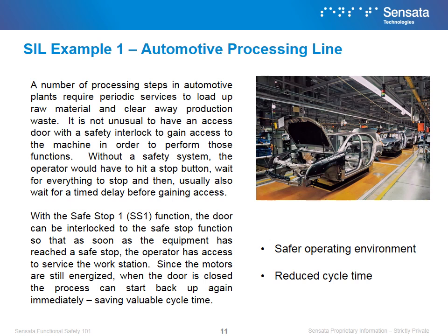With the Safe Stop 1, SS1, function that can be provided with a functional safety encoder and safety controller, the door can be interlocked to the Safe Stop function so that as soon as the equipment has reached a safe stop, the operator can have access to the service workstation. Since the motors are still energized when the door is closed, the process can start back up again immediately, saving valuable cycle time.